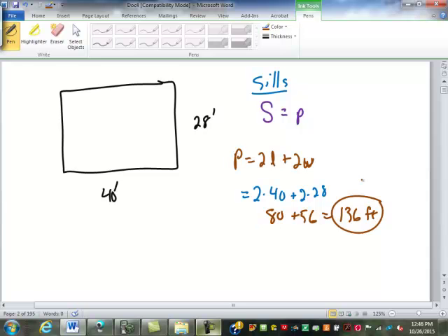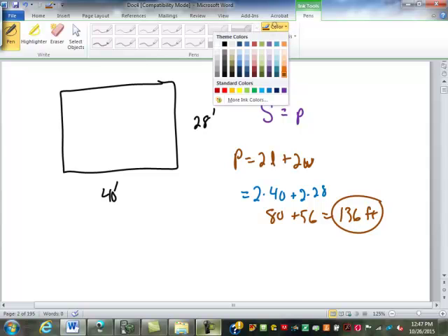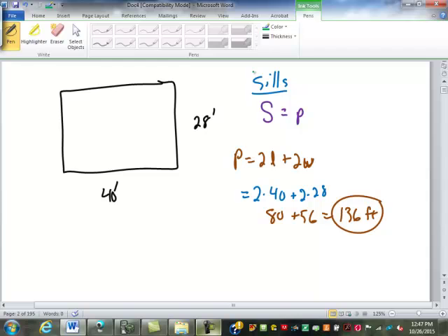Usually you use at least 2x8s, 2x10s, depending on your preference. This is the foundation, the concrete. Your sills go on top of the concrete foundation. Even if you don't have a basement, though, you're required to have a crawl space in most places, unless you're on a slab. But if you're on a slab, you still have to have a sill on the concrete. So anyway, that is the linear footage of sills required.